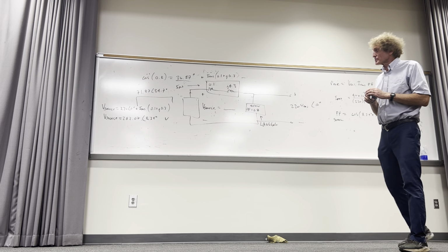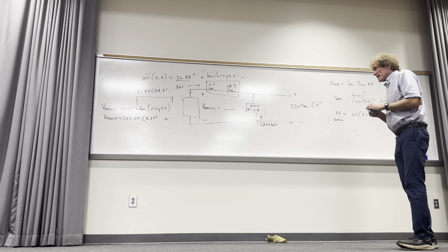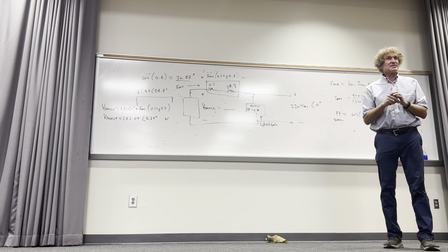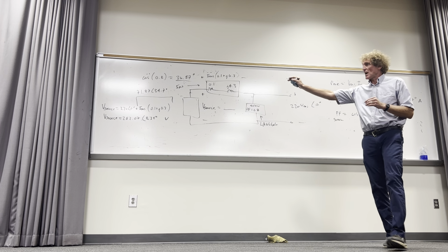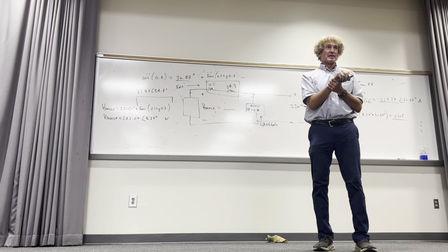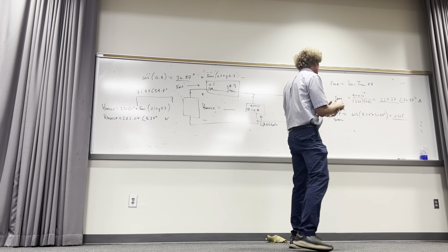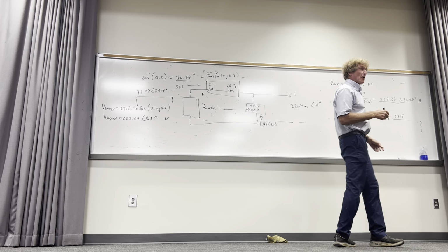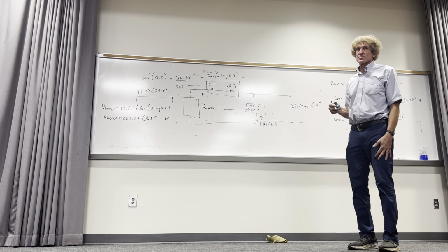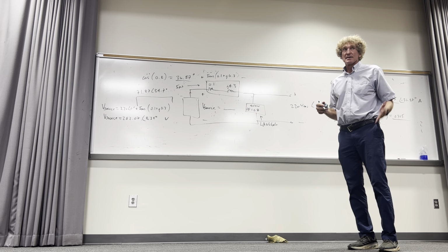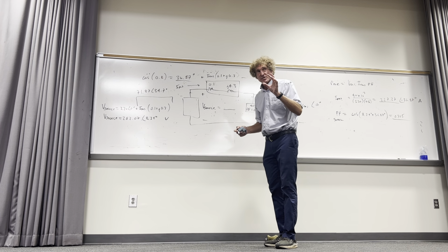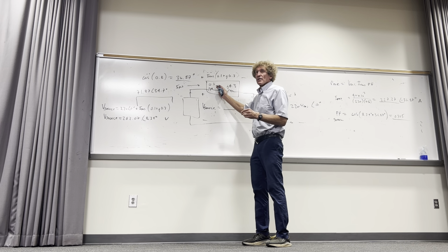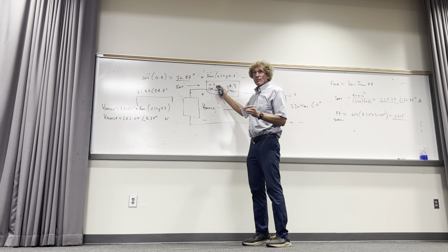Never can tell them. Okay, so here's the question, and this is the question that's not asked directly, but I will ask it. How much real average power is supplied by the source? Well, you know it's at least what? 40 kilowatts, right? But what do we have to do, class? I'm just doing this one more time to reinforce it. You have to take the magnitude of IRMS and square it times 0.1. Isn't that right? What would that be, by the way?